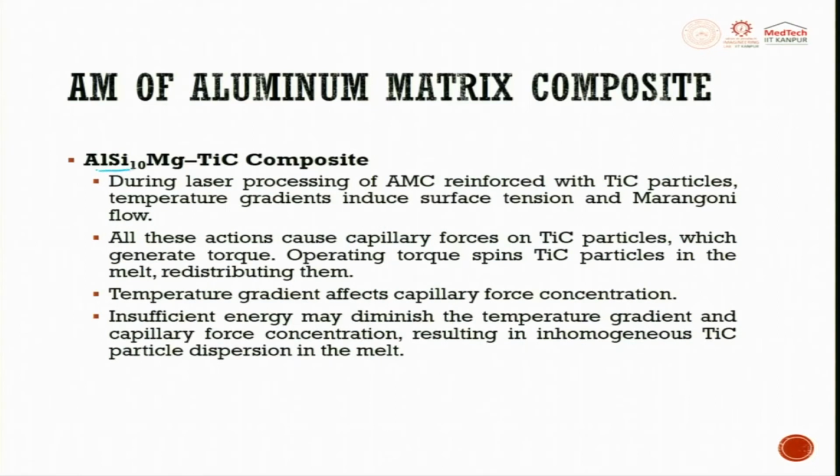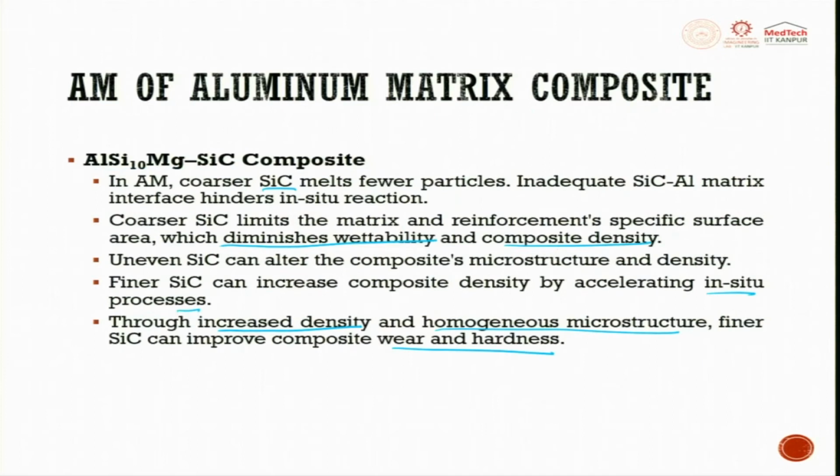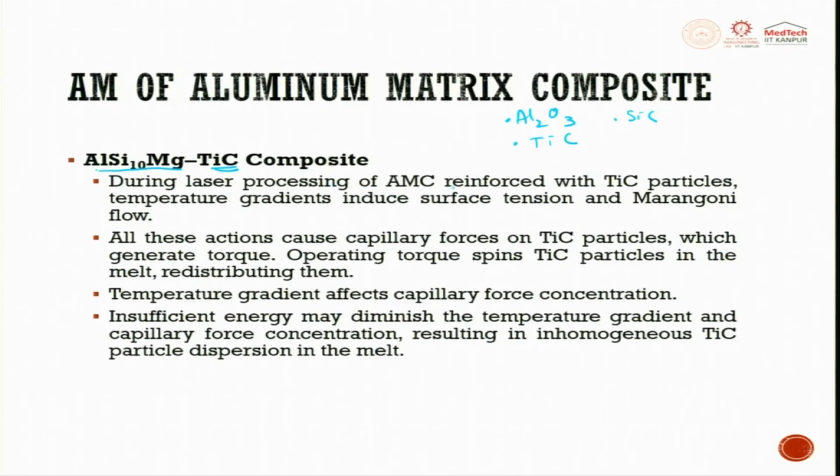Now, AlSiMg with TiC. We saw with alumina, then we are going to see with TiC. We also saw with SiC, the previous one. During laser processing of additive manufacturing composite reinforced with TiC particles, temperature gradient induced surface tension and Marangoni flow are very important.